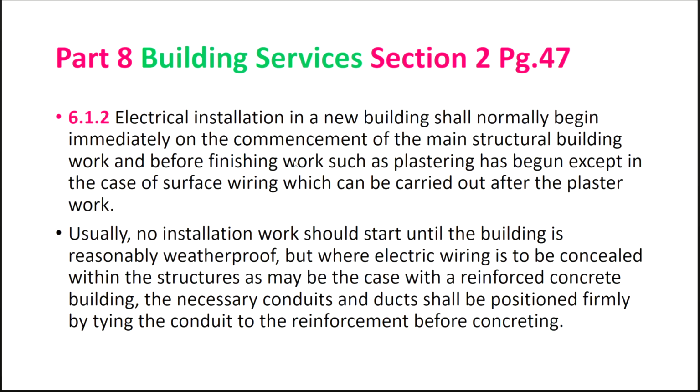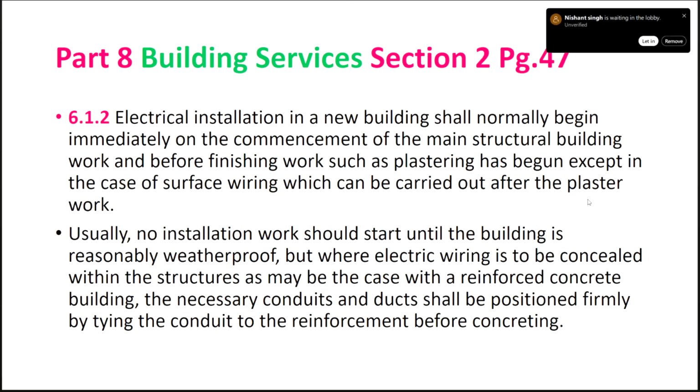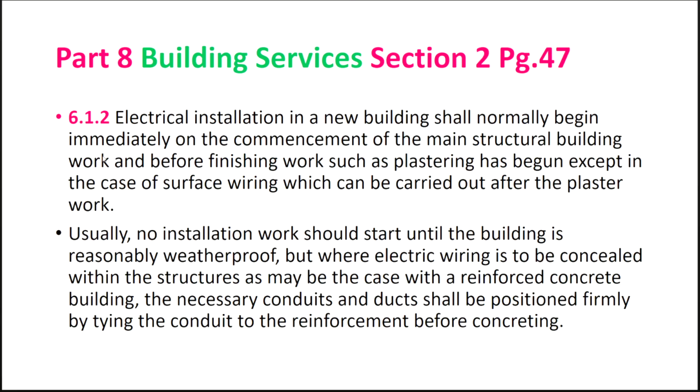Electrical installations in a new building shall normally begin immediately on the commencement of the main structural building work, and before finishing work such as plastering has begun, except in case of surface wiring which can be carried out after the plaster work is carried out. So I am reading NBC provision part 8, section 2, page 47, building services. Usually, no installation work should start until the building is reasonably weatherproof.